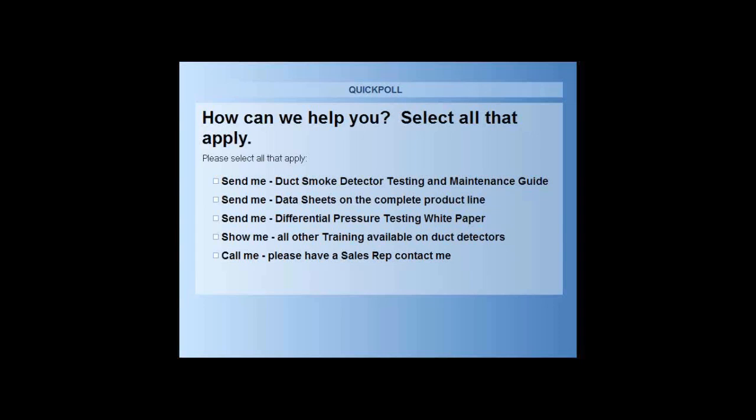Okay, all right, thank you. Next question, how many feet away can a remotely located detector be installed from a power section? Just to clarify that question just so everyone understands, they're asking when you're using the split configuration or the 2-to-1 configuration where you have your sensors mounted in the airstream and your power board mounted in a more convenient location. The distance between those two sections should not exceed 1,000 feet.